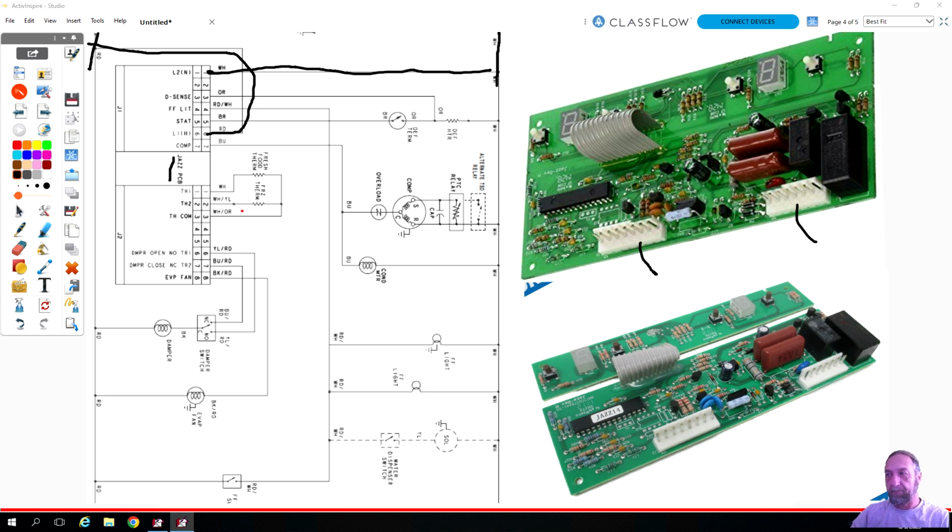You guys can all see that? So here is the same jazz board that is in the picture in the diagram. This diagram's off of this refrigerator. So in order to get to it, the board's underneath here, which means I have to pop this all open and get to it. But I did something different. I gave it power from here. How did I do that? The connector that's in your hand. Okay, but where would I do it on this connector? The red wire and the white wire.